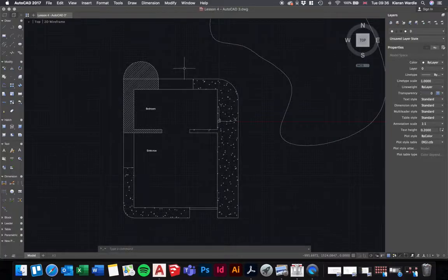Or because the drawings that you're going to be doing are going to be a bit simpler, purely because of the fact that they're not going to get built, you can actually just choose layers that identify thicknesses, for example. So you could choose 3 or 4 layers, and one could be a thick line, one could be a medium thickness line, and one could be a thin line. And then maybe you could either have a grey line or a dotted line to give yourself a little bit more flexibility.